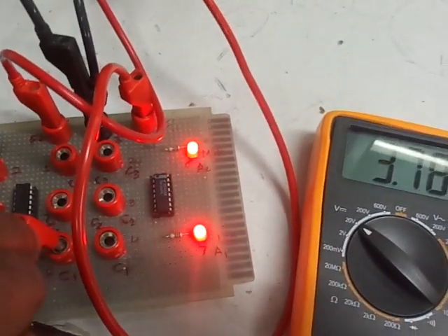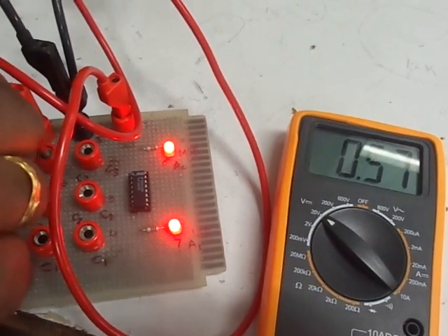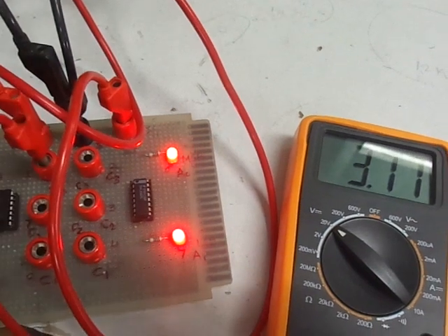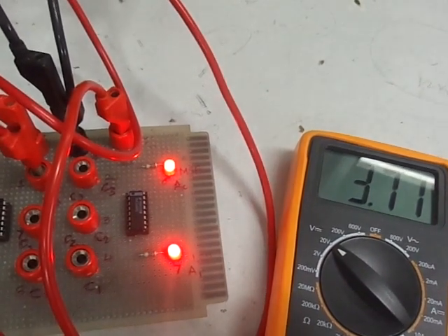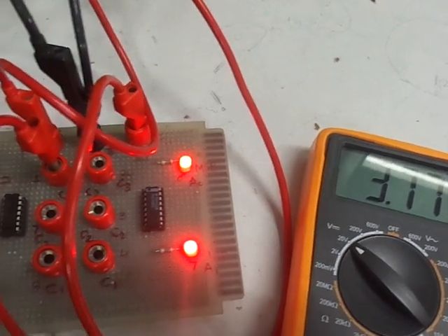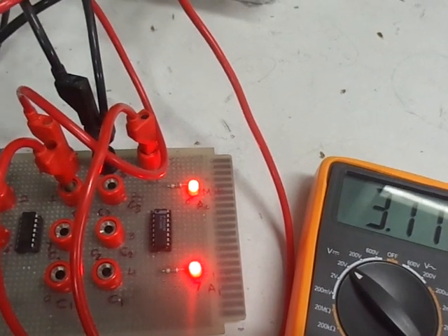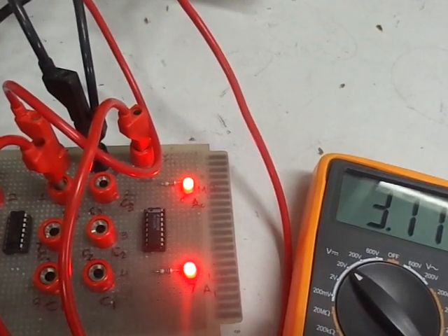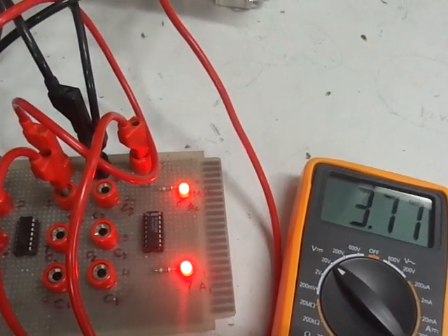The output of comparator 1 is 3.8, and this is 3.8 and this is 3.8. This means all the comparators C1, C2 and C3 are turned on and the output is 1 1. So when the input signal is greater than 750 millivolts and less than 1 volt, the output we get is 1 1. Hence, as we have defined theoretically, the conversion of the analog signal into a 2-bit digital output is obtained.